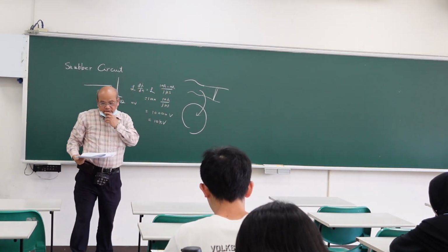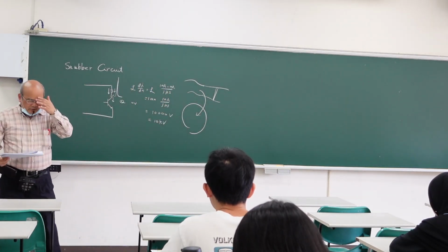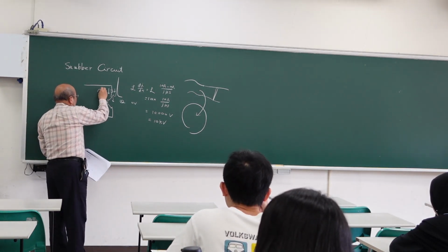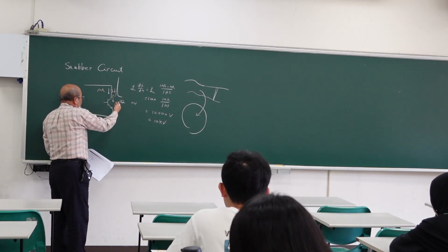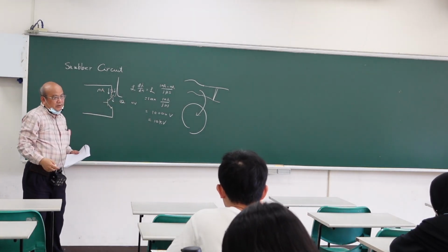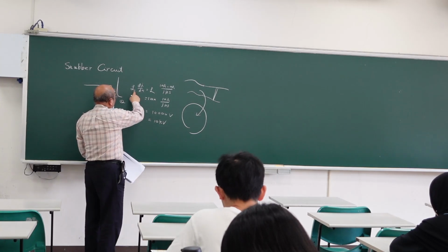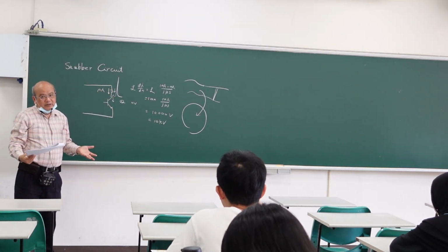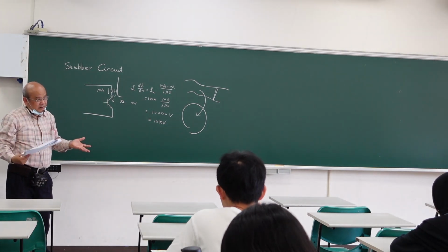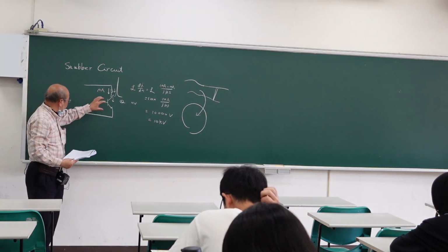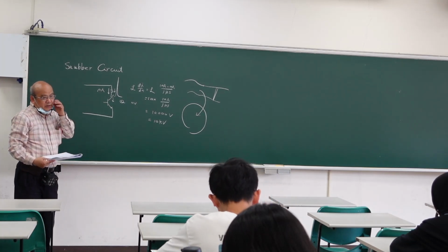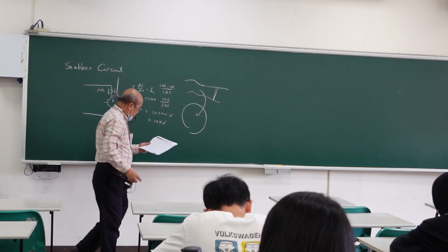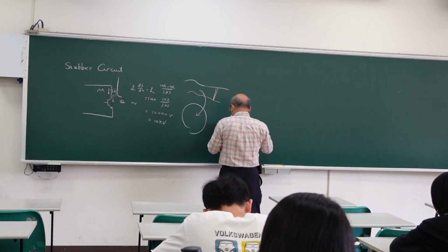So if you turn on a switch for an inductor, then you can get 10 ampere. But when you turn off, you have no path. If you have no path, you create a spike. Then you damage your device immediately, and the next time you try again, you damage it again. So there is no way to solve this problem. So now we want to discuss the details.